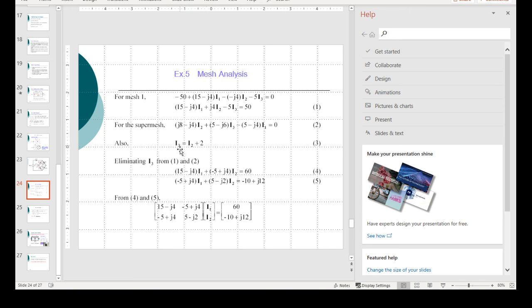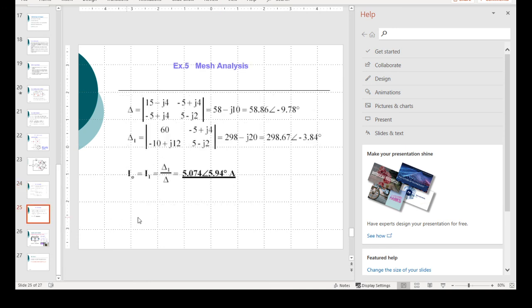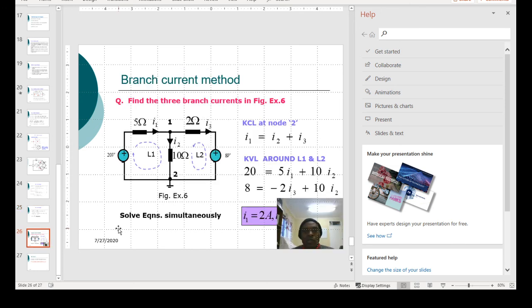So we can use this equation now to eliminate I3 from the first 2 equations. And once we eliminate I3 from the first 2 equations, we have got 2 equations in 2 unknowns, I1 and I2, which we can assemble as before in matrix form, or proceed to simplify using elimination. And since we are only required to find I0, I've used Cramer's rule here, and this is what you get for your answer. Then we are almost home and done.